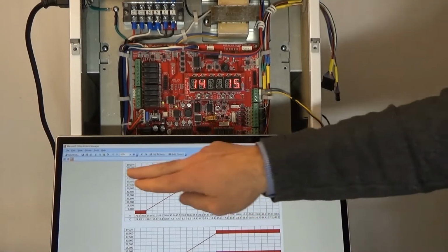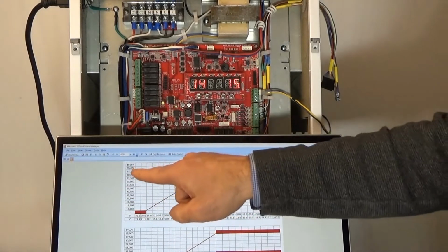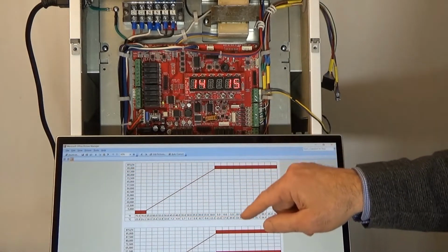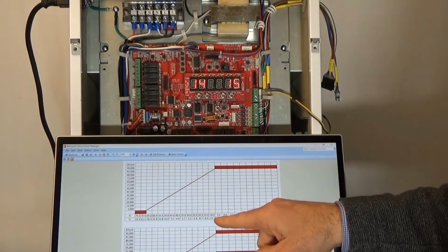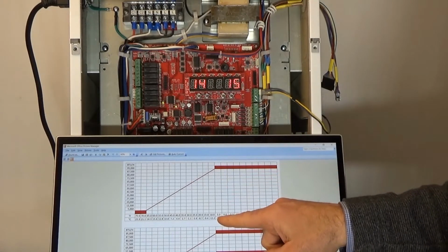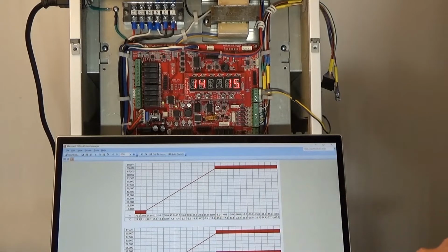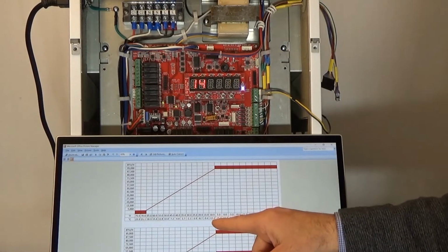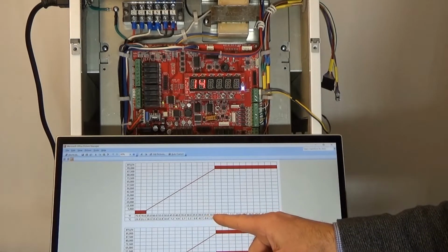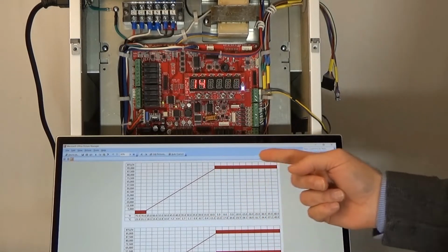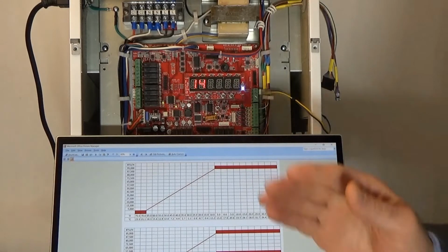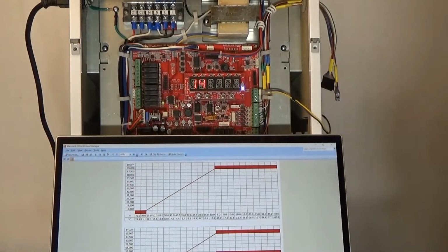So here we have our 18,000 series unit. Again, we can deliver 99,000 BTUs. So we look at what temperature do we need 95,000 BTUs, and here we've set it to 5 degrees Fahrenheit or minus 15 Celsius. So at any temperature below that, you'll be running at maximum 95,000 BTUs being the target delivery.